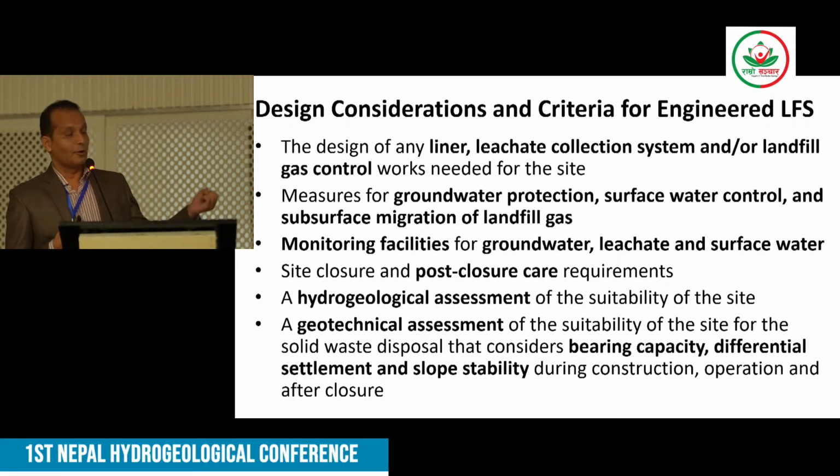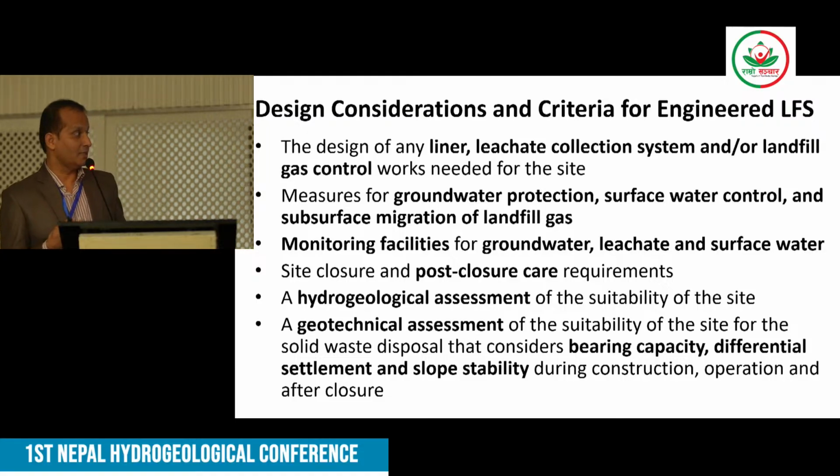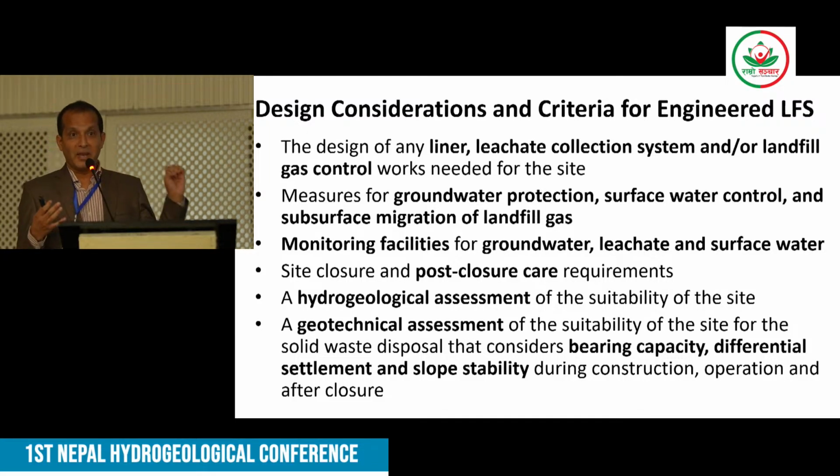And the site closure and post-closure plan is also very important. After 10 years or 15 years, even 20 years, the gas is still being generated. Even the leachate is continuously generated, and you have to continuously monitor this groundwater well as well as other leachate sources.